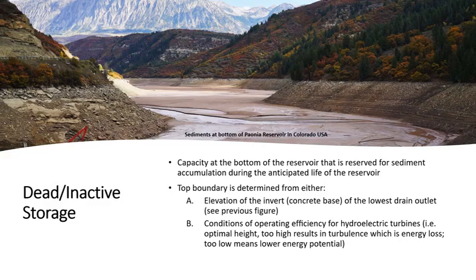Now let's talk about the dead storage. Dead or inactive storage is the capacity reserved to account for all the sediments that will accumulate at the reservoir through its anticipated life. So you're looking at least 50 to 100 years of life of the reservoir.